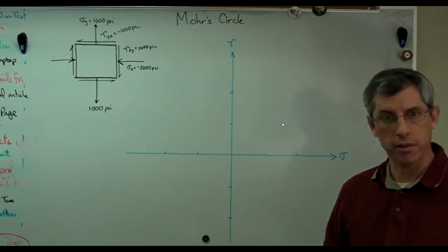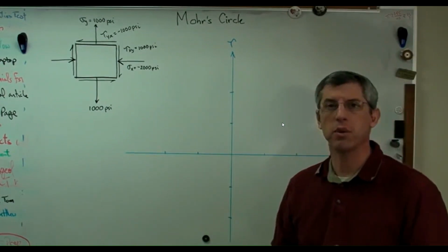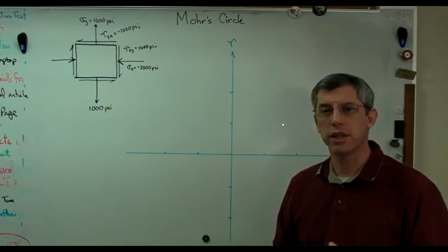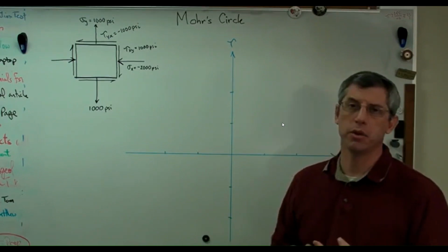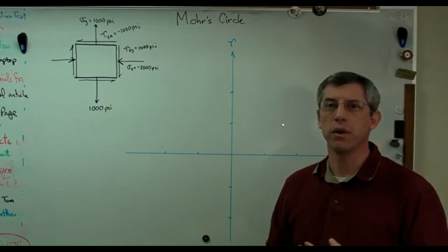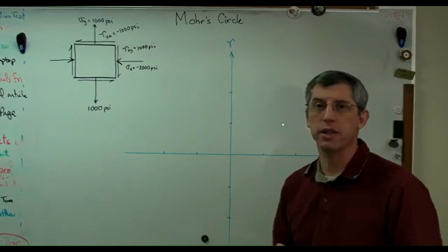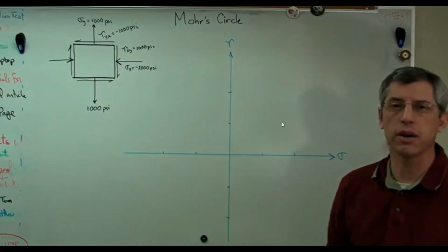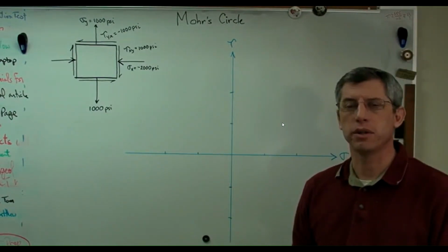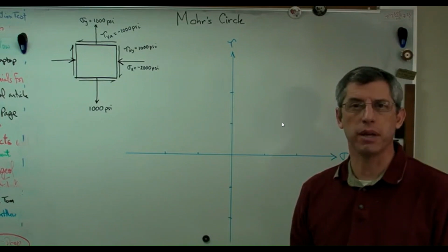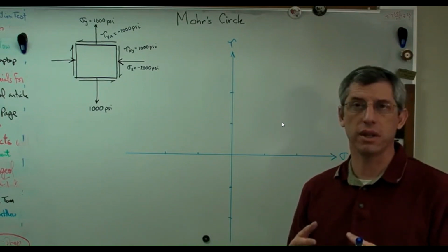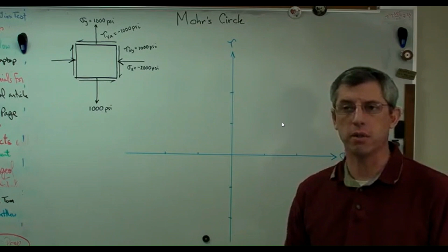The big picture, the important thing about Mohr's circle is it lets us calculate maximum and minimum stresses without knowing necessarily beforehand what angle they're at. We pick x and y axes really for convenience. If we calculate stresses on a part, we're going to set up some coordinate system that's maybe aligned with one of the axes of the part.